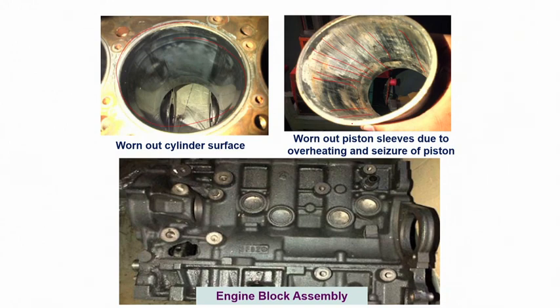One of the key design elements here is to make sure you have enough lubrication between the piston and the inner bore wall, so that they don't come into direct contact with each other. A very thin lubrication film should make sure that they don't rub against each other non-uniformly. So the function of the engine block will to a large extent depend upon the prevention of wear at these positions.